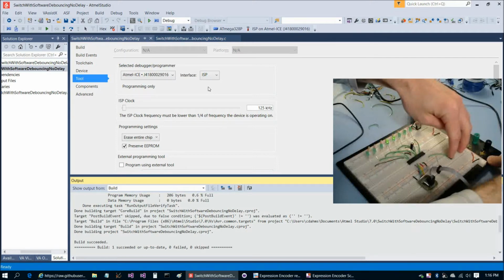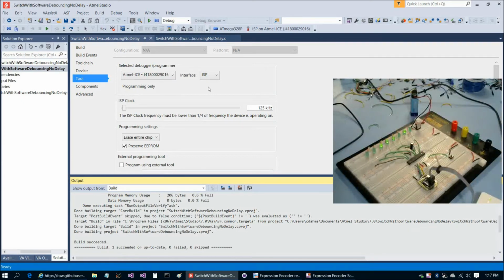The problem with this program is that we are not using a delay. So as you see, we have to check 8,250 times to constitute receiving one switch press. And if our chip was doing significant activities otherwise, that really would be an awful lot of time spent just looking at a switch. So what we're going to do next is we're going to add in a timer.